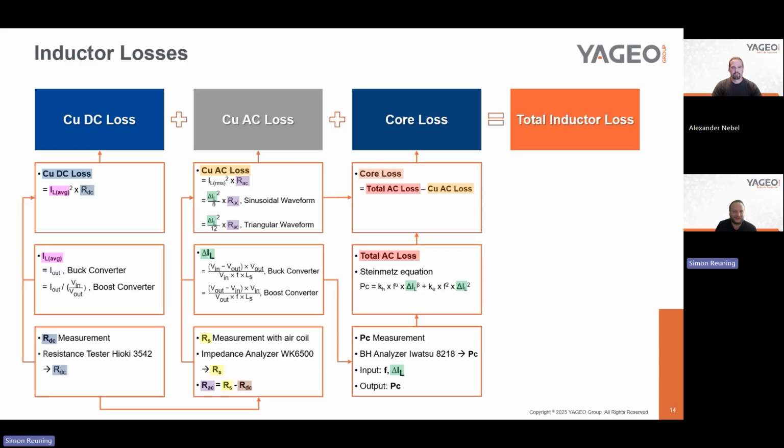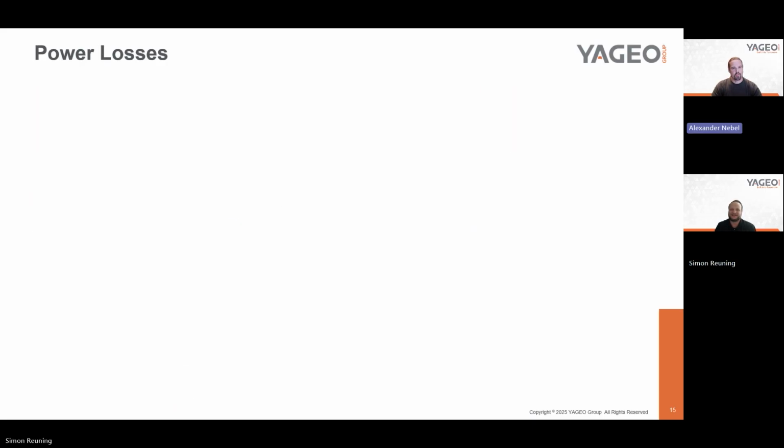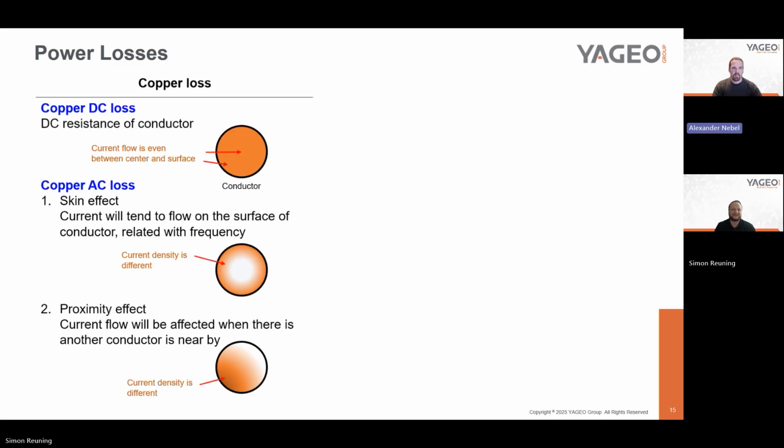Well, looking at this slide, it kind of makes me dizzy looking at all these equations. Do you have a better way of describing what these losses actually are? Yeah, for sure. For anyone who doesn't understand all the deep mathematics, we can split the three losses into an easier way of understanding. The copper losses are just the DC resistance of the inductor.